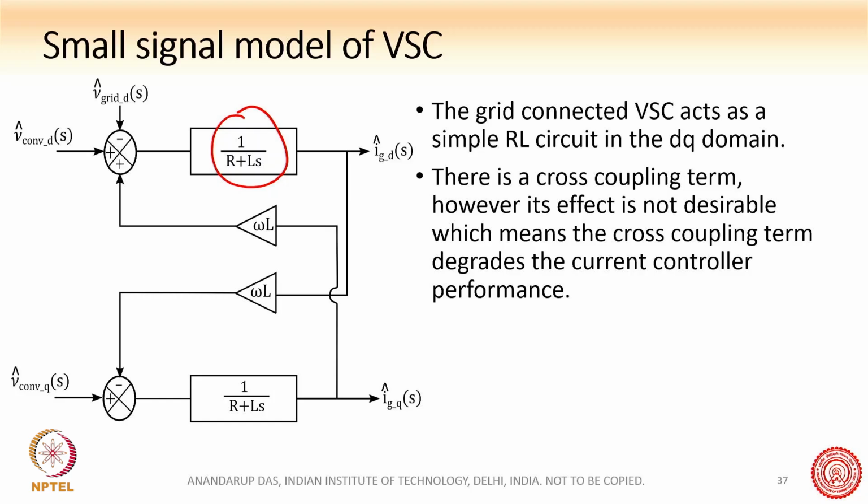So they turn on and turn off very fast. In a similar way, present day microcontrollers can easily work at say 100 or 200 megahertz. So the delay in the whole processing system is small, and the switching frequencies of the devices are very high nowadays. With silicon carbide MOSFETs, it is very common to see 50 kilohertz or 100 kilohertz switching frequency.